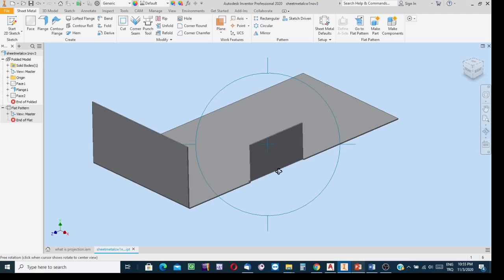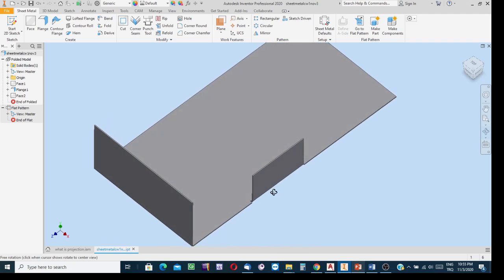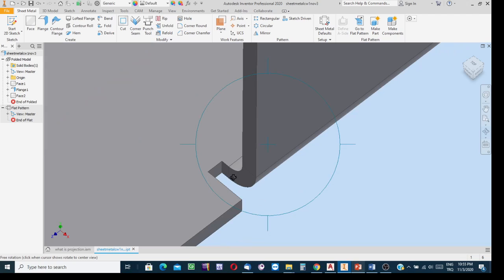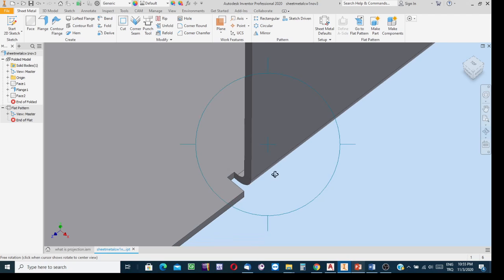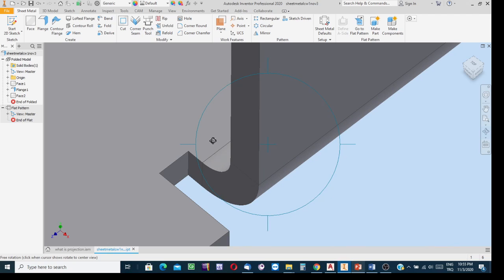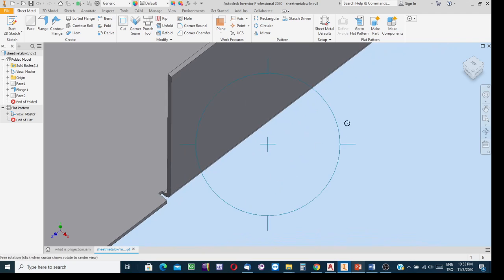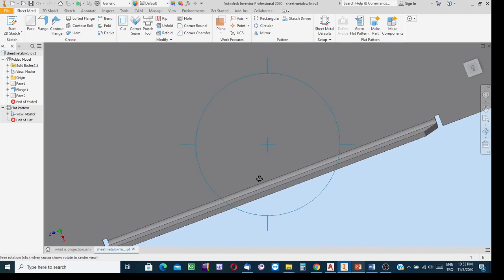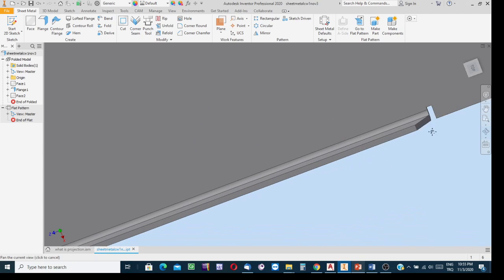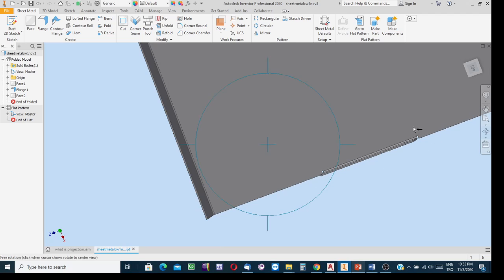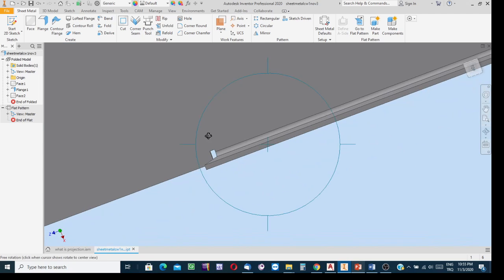Then, to be able to prevent tearings, we need to have reliefs. Zoom in, and then see that the necessary relief has automatically been created here. And also the bending allowance, this transition part, has been perfectly created by the software. At both terminal portions, you see we have such cuttings to be able to prevent possible tearings. These are needed. These are strongly recommended. And this relief has been created in the standard common size.